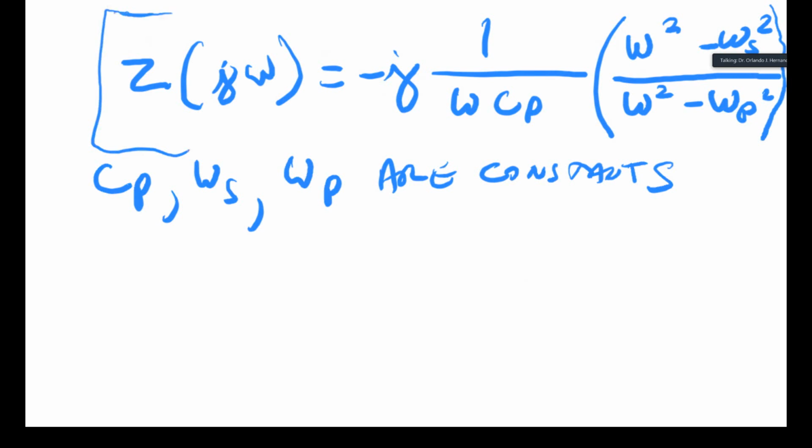So that gives us something to work with, and it's really good information because the crystal by default is set. So you cannot use a crystal for any frequency. Each crystal will have its own frequency that it is optimized for, and you will use it as a feedback or beta mechanism with an amplifier to make oscillators.